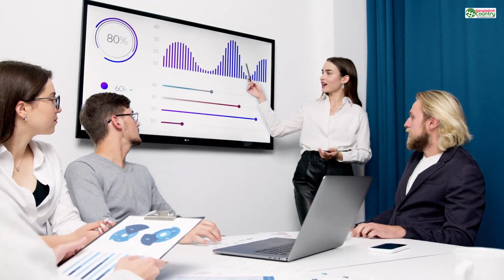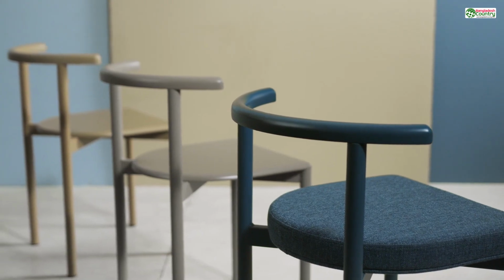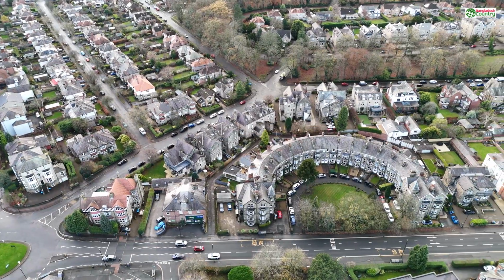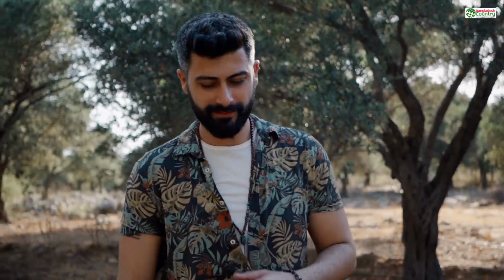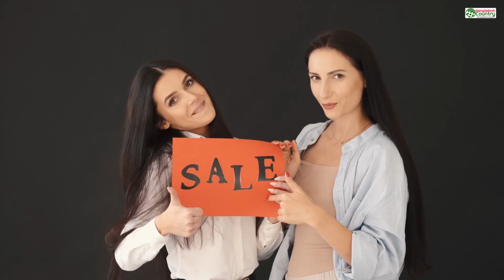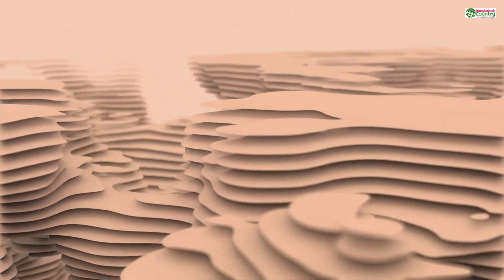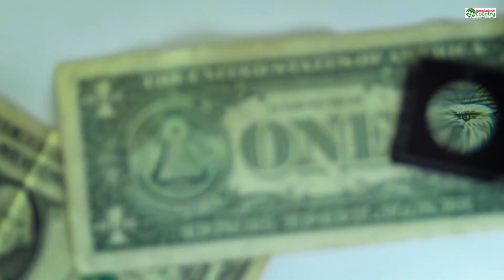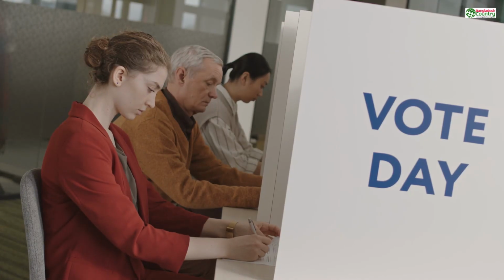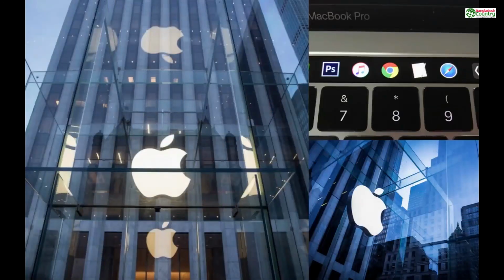Function over form. This leads us to the middle ground, the Goldilocks zone. This is typically around 0.2 millimeters. It's the default setting for a reason. It offers a fantastic balance. The layers are fine enough that the part looks good, but not so fine that the print time and cost become excessive. For the vast majority of projects, desk organizers, custom cases, general-purpose gadgets, a 0.2 millimeter layer height is the sweet spot. It's the reliable workhorse of 3D printing.